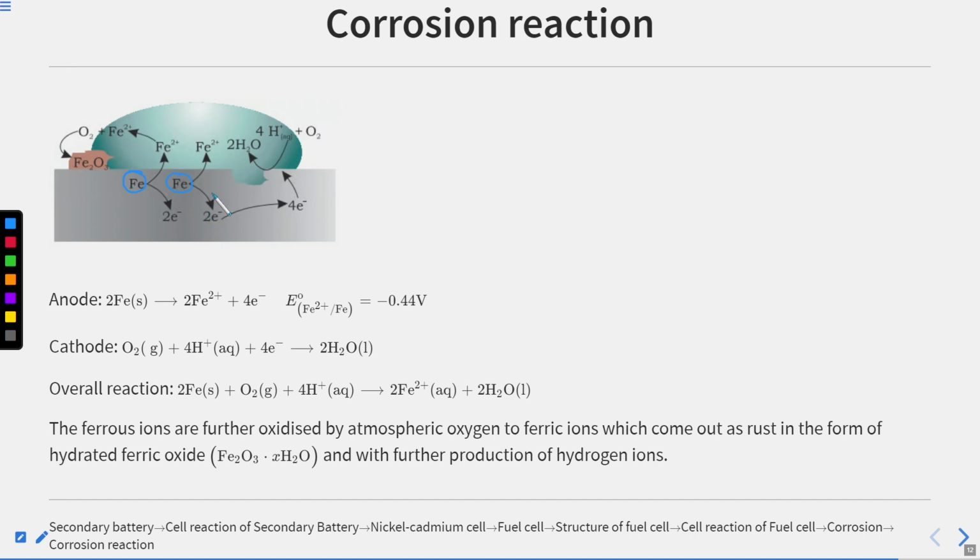So we are just looking at the final reaction. Suppose here is the iron. What will happen? This iron will lose 2 electrons. So 2 such irons will lose 2 electrons each and generate 4 electrons. Now this iron will go into water in the form of ions, and as it is dissolved in aqueous, this Fe2+ aqueous is present. Now this Fe2+ aqueous will take oxygen from outside, from the environment, and form your Fe2O3, that is your ferric oxide.